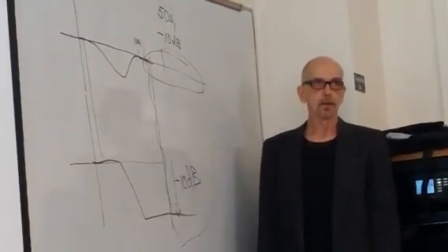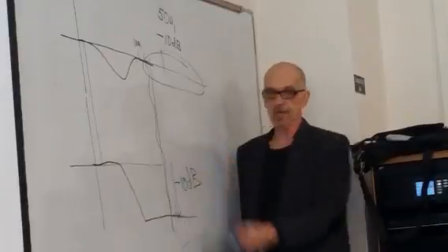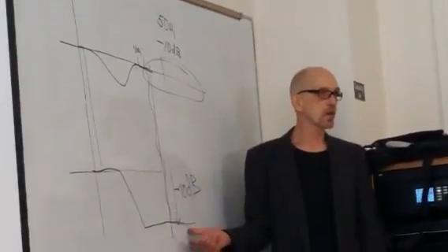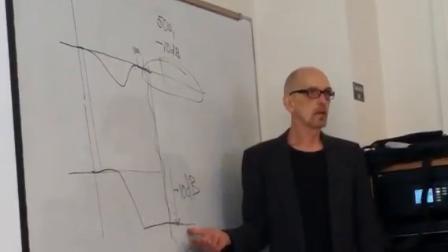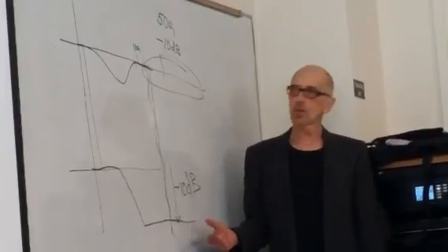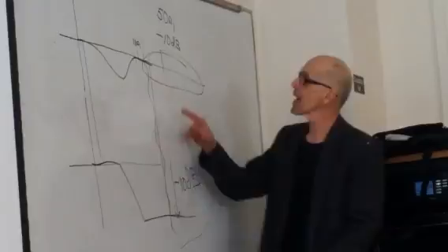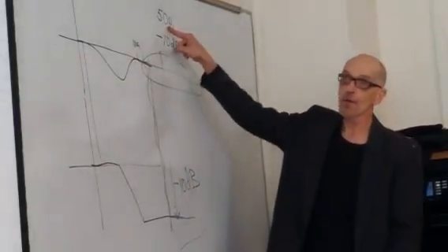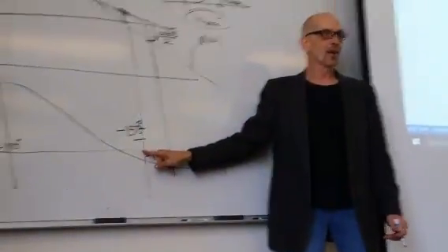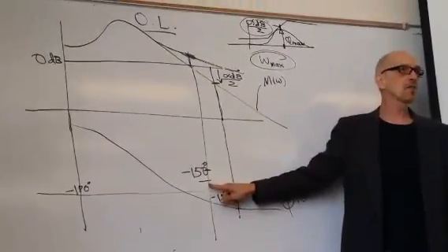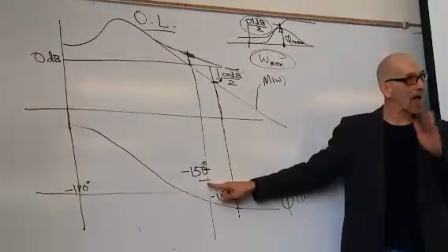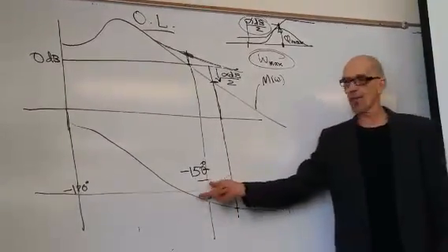Okay. So how do I design this compensator? Well, I've got my two equations right here. You choose, remember, there's the frequency. What is 50 omega 1? 50 omega 1 is this guy. Because that's where I want the phase of my lag compensator to be back to 0. So that gives me one equation.